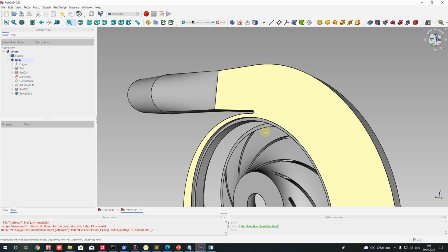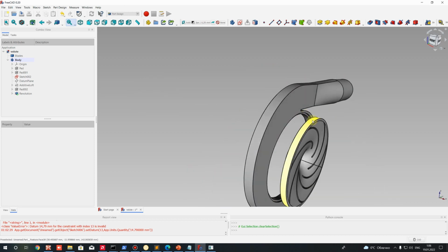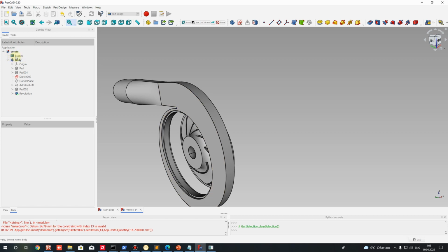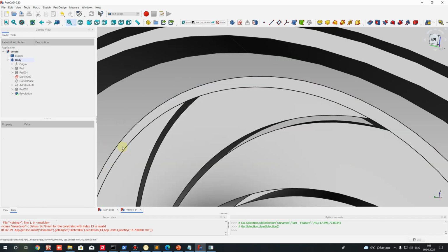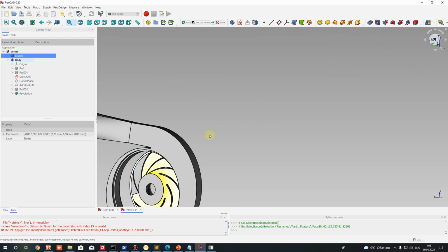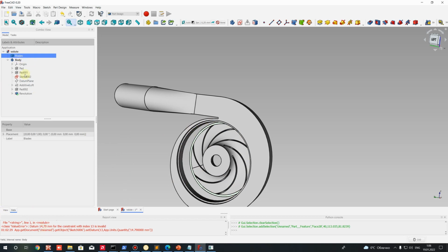And now we can set the right position for our impeller and for our volute in the X direction. So for this, let's calculate what position we have for our impeller. Let's choose this surface. You will get 40 millimeters. For example, if I just show this line, go to the information for our face, it will be 40 millimeters. And we have to go to position 0 and minus 40.